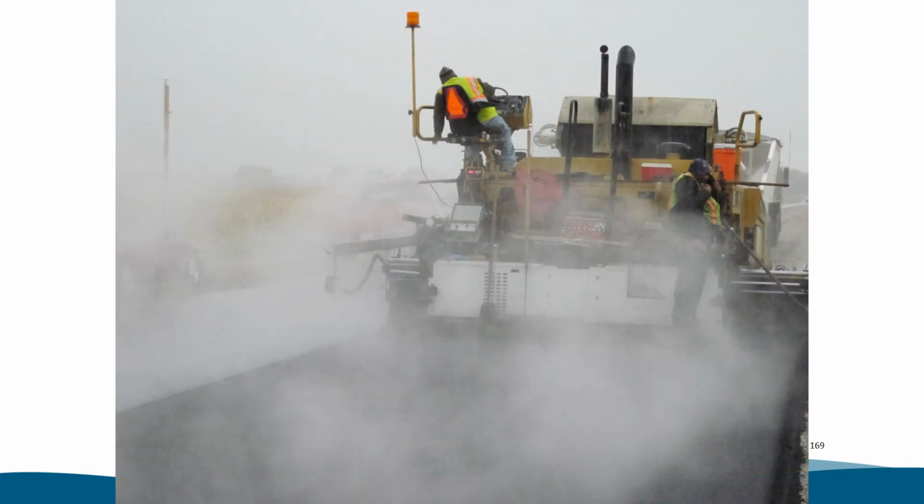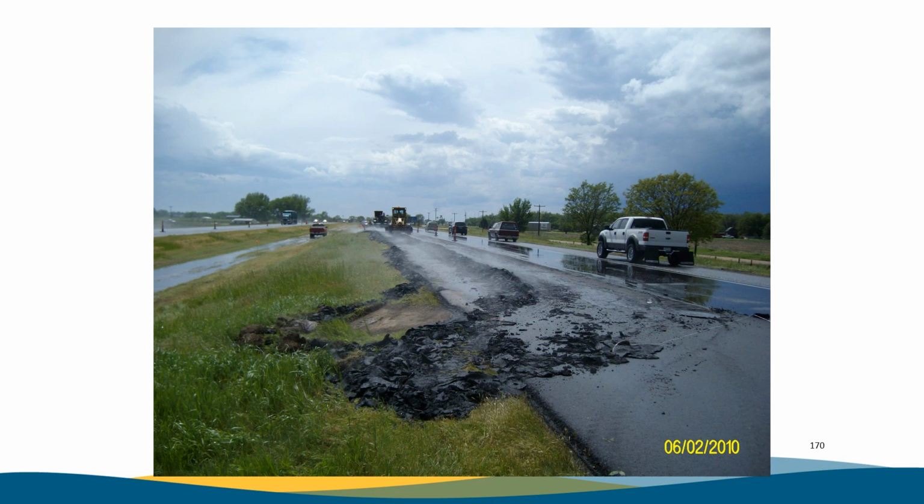What can they do during the paving operation? Pump the brakes, that's for sure. The contractor stopped the paver and held the trucks that were tarped up until the storm passed. Here is a photo just after it stopped raining. You can see in this photo the fast-forming storm moving off, but leaving a mess. Here you can see the contractor's motor grader used to blade up the hot mat for removal of the freshly laid material.